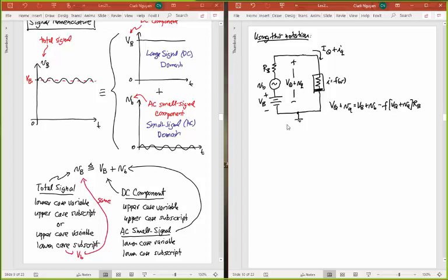So that now becomes the equation that is governing the performance of this circuit. Now, we haven't solved anything yet because this thing is still nonlinear, right? But now that we've split this into large components and small components, we can take advantage of Taylor series. We can use a Taylor series approximation for this function. And if we keep voltages small, which is the idea behind this little vq, we can linearize the whole thing. So let me write this.